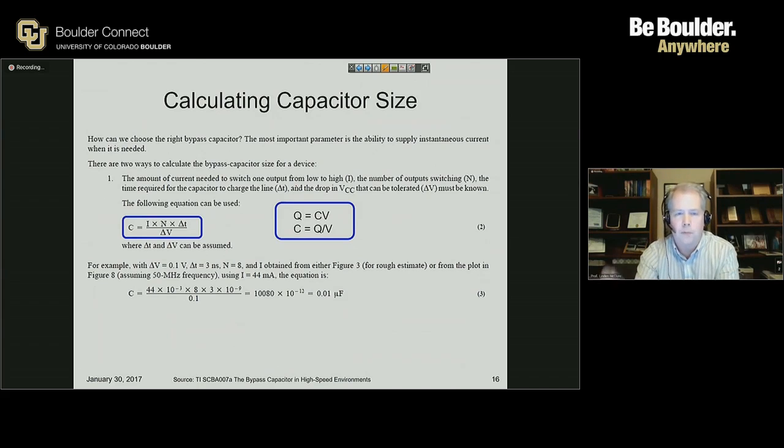So if a chip has a line that transitions and requires a quick burst of current, the charge can be supplied by that local decoupling capacitor, and then it can refill from the bulk decoupling capacitor, which provides charge to replenish the smaller high frequency capacitor. So charge gets passed along to the destination, but it's done in such a way that the amount of noise seen on the VCC line is minimized. It's a very low amount of noise.